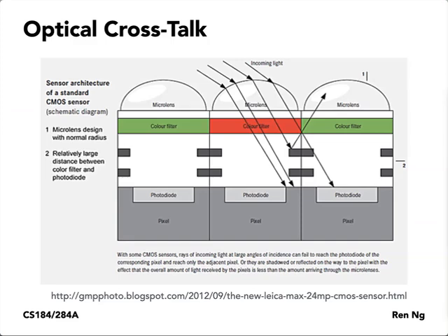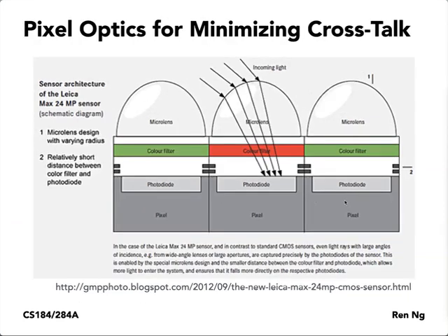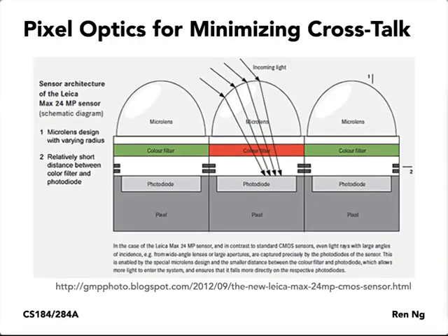So what should have gone through a red filter to arrive at a red photodiode, so to speak, is going through and getting added up to a green photodiode. That's kind of a problem. One way to try to mitigate this is to use semiconductor engineering to shrink the depth of this, make the wire layers shorter, put a bigger microlens on it to bend the light more, effectively towards the photodiode. So these are some techniques that sort of happen.